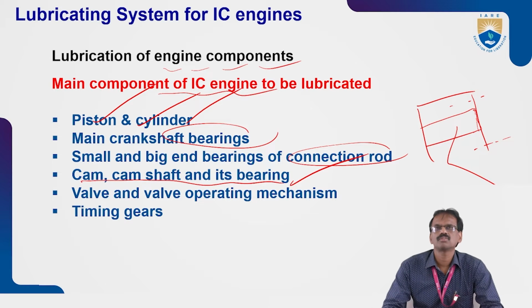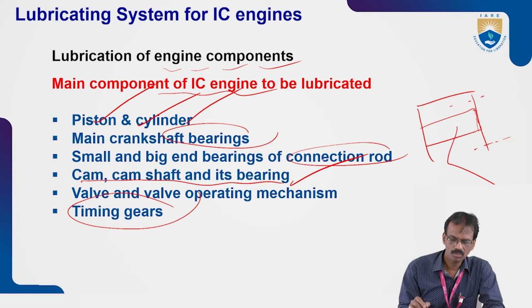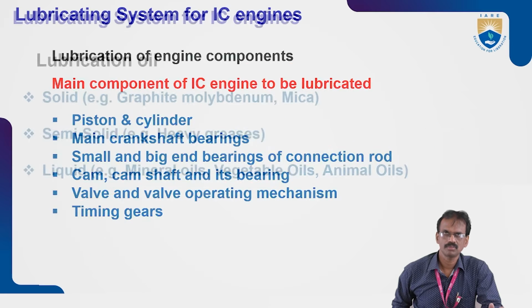For that purpose also, we use the lubrication system. Next, valve movements: valves opening, valves closing, inlet valve opening, inlet valve closing. To provide an effective valve operating mechanism, we should provide the lubrication system. Timing gears also. So these are the main important parts to be lubricated for the long life of engines.